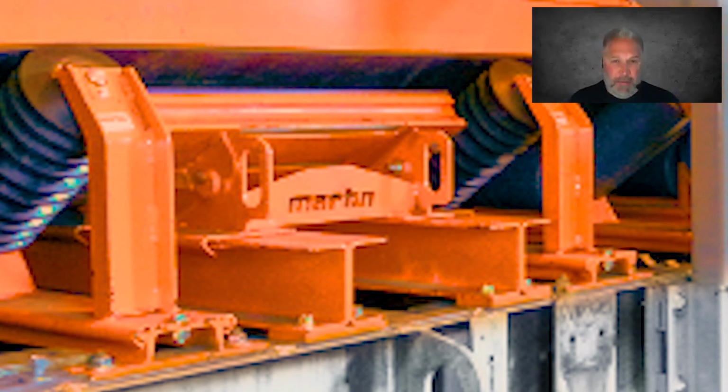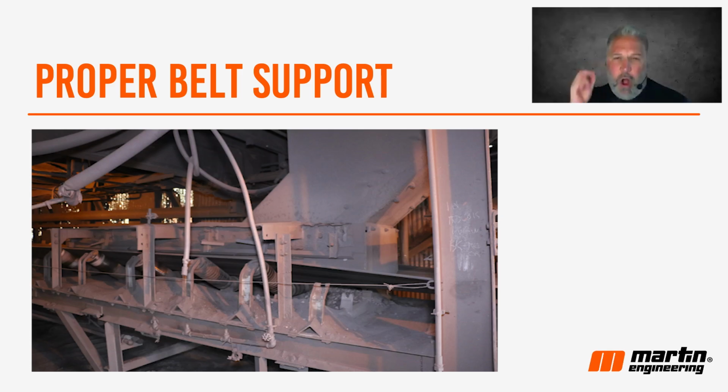Every situation is going to be a little bit different, and it really takes a trained expert to be able to give the guidance on how you might need to support that belt. One thing that I often see facilities do to try to eliminate that sag is to put excess stretch on the belt. They think if they pull that belt tighter, it won't sag from idler to idler. That's problematic. You don't want to do that. You want to have the correct tension on the belt and not overstretch it.